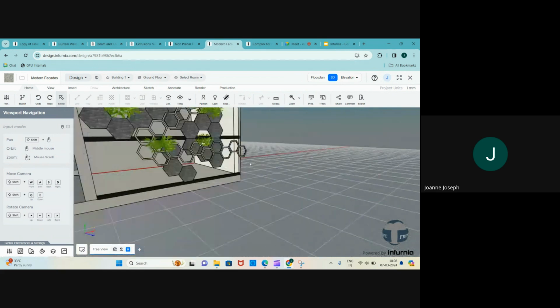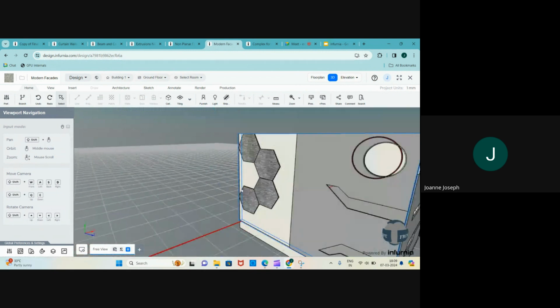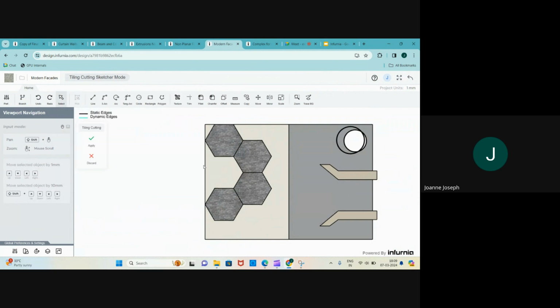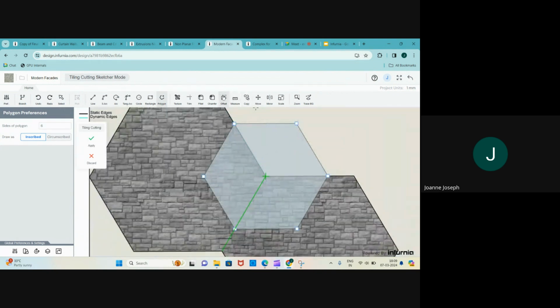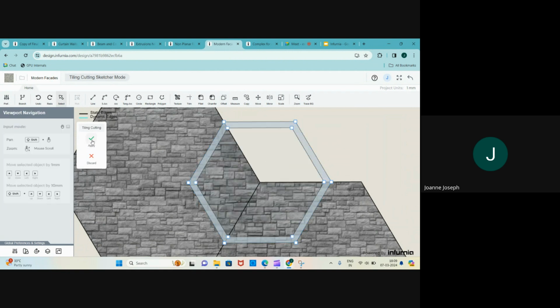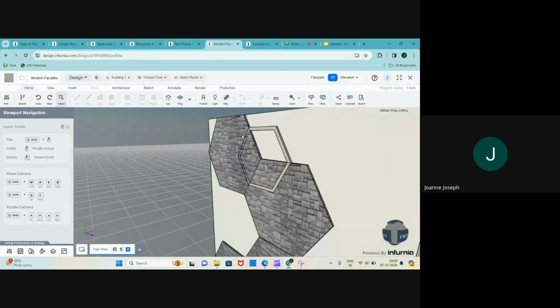To create these sort of shapes, you can simply use the offset tool, but the same principle. Once again, I go to add polygon and I choose this sort of hexagon. Using the offset tool, clicking inside the shape and determining your offset radius, 30 I'll say, selecting apply here. And now if I go back, it's buried inside this.